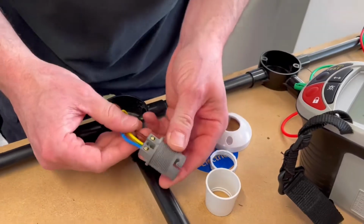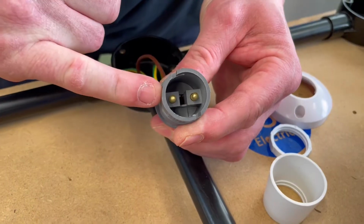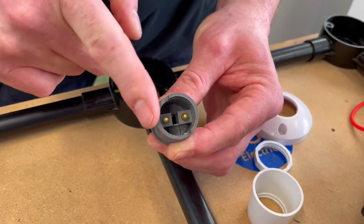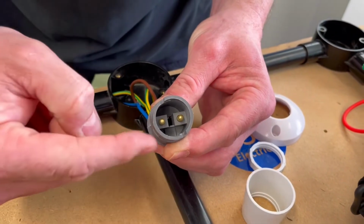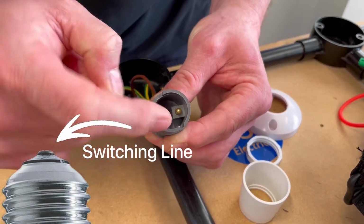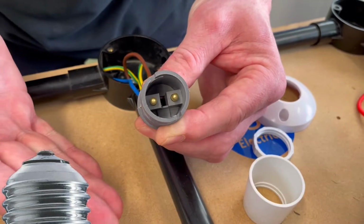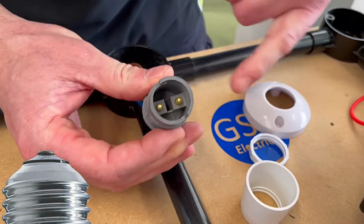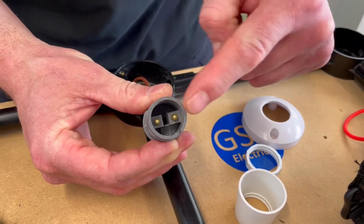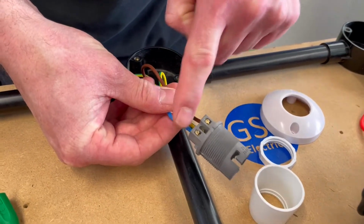So if we break that down, we can see that we said in a previous video that this actually has no polarity, because this takes a bayonet cap lamp, so it doesn't matter which one of these is line and which one of these is neutral, and it would be a switching line and neutral. However, if you had an Edison screw style lamp, you would have only one center pin and the screwed section would be a different conductor. So the center pin, if you only had one, would be the line and the screwed element would be the neutral. But often at college in the early days, you're using lamp holders that take bayonet cap and these have no polarity. So when I look this side, it doesn't matter which way round the blue and the brown ones were.